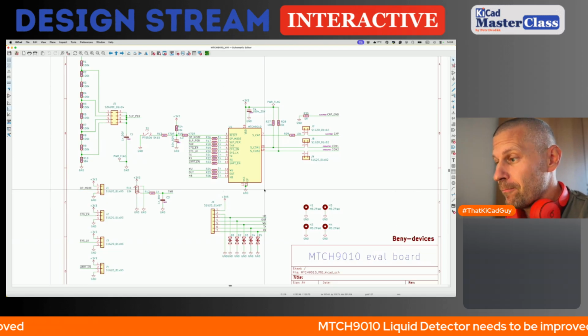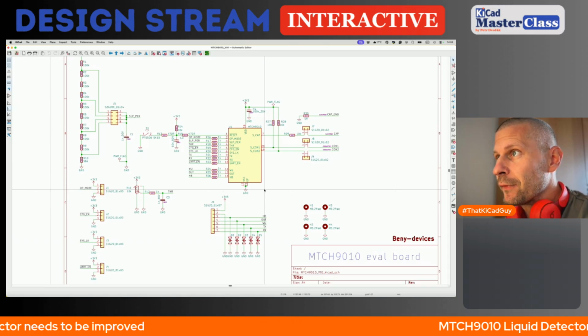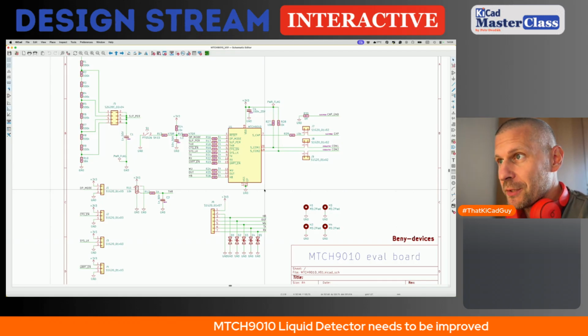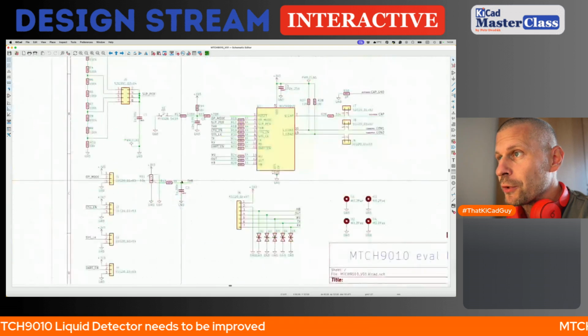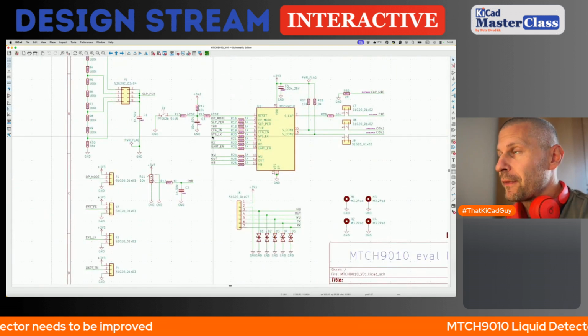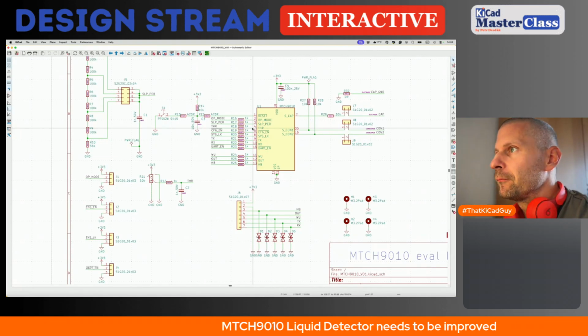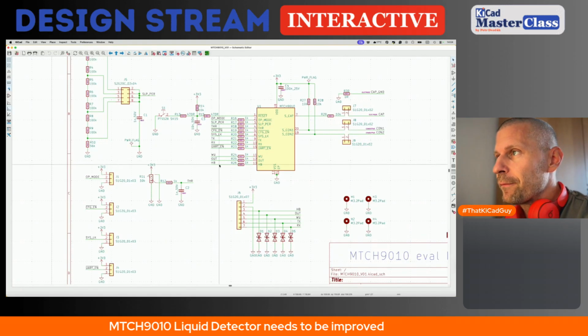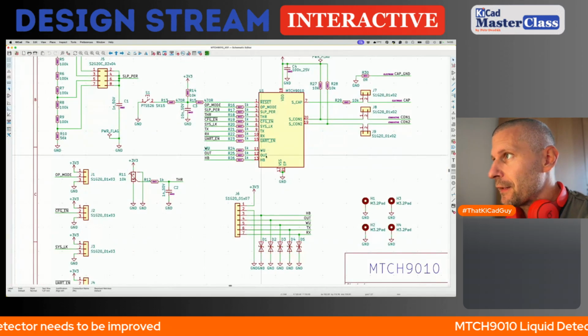And I believe I will monitor with a few LEDs all the outputs. And probably, yes, all the outputs. And I think a few test points are missing as well. For instance, near the threshold output, output of the trimmer, input of the IC. I will monitor the heartbeat signal, the output signal, and the wake up. I think it's a wake up.